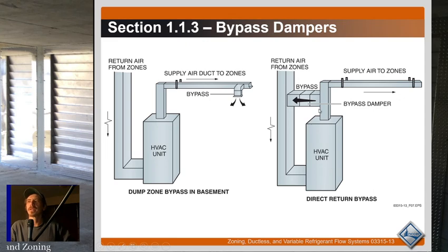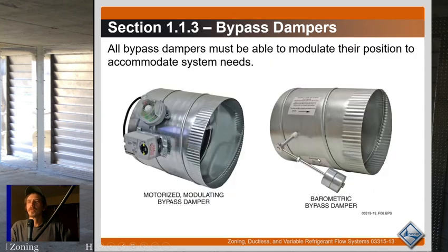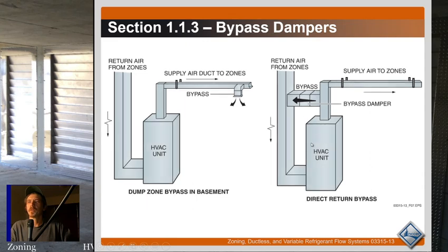That furnace is normally going to have about 120 degree air coming out of it, right? 120, 130 degree air. And if you're dumping 130 degree air back into the return, depending on how much you're pushing, you're going to quickly have 150, 160, 170 degree air, and that is not good for a furnace. So that's why you have the discharge air sensor to cut that system off once it starts exceeding what you really want that air to be, and you're going to want to set it to whatever the furnace manufacturer's maximum heat rise is.